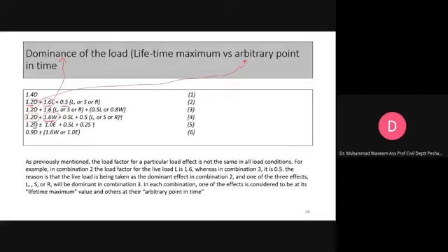This was not performed on arbitrary data. There was some original experimental data, and they have used the reliability theory to derive these load coefficients, and that's why they have put that into the code. And obviously they have tried to go to the safer side, for example, if the load factor is 1.2, maybe they have shifted it to 1.6. Maybe you have seen in statistical analysis there is a mean and one standard deviation plus and one standard deviation minus. So this kind of stuff has been used to come up with these factors. This is what I can tell you, but I can go into the detail again, and I can get back to you if you are not satisfied.